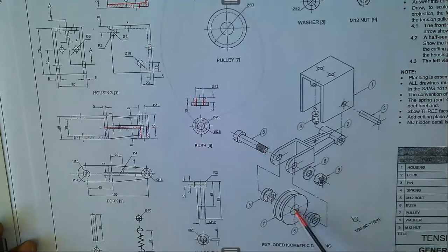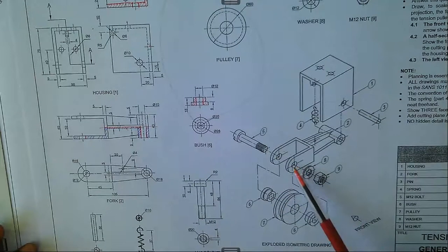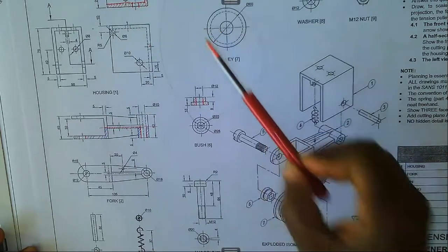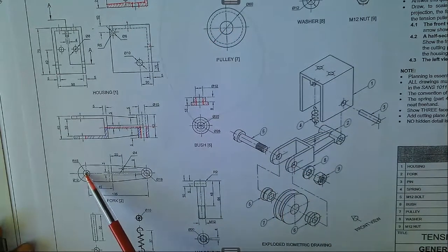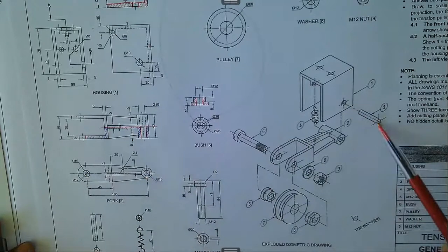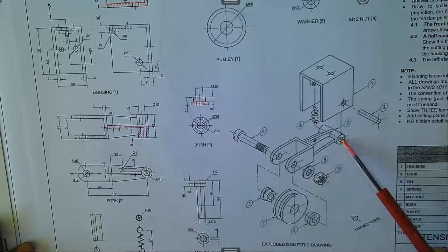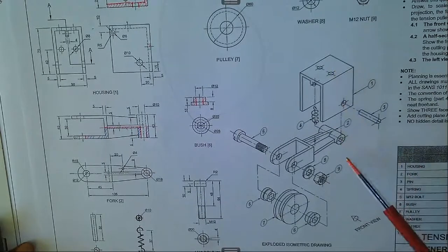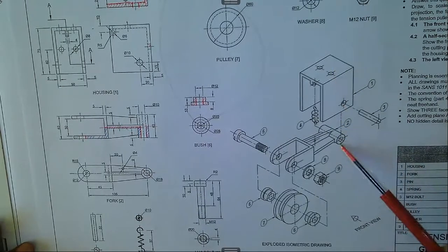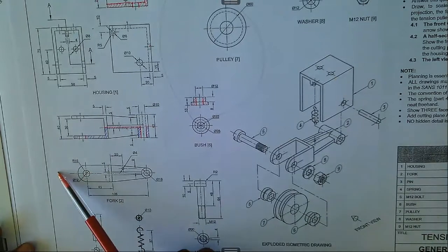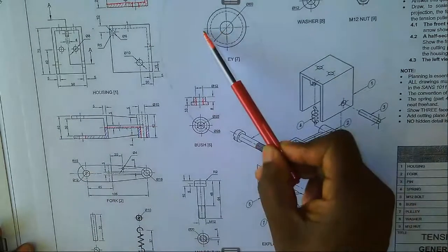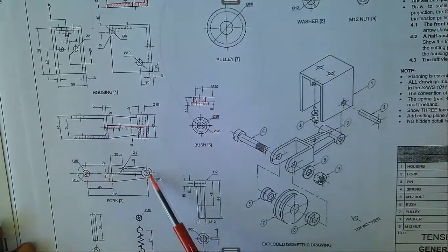So the distance from here to the center line of this one, this point is going to be right there. So what we need from here to the left, we need 30 millimeters, which is from here to there. And we are also told that from this center to that point, which is also going to be aligned with the housing, from here to there we have got 30, which is the 34 for the pulley. Then from here to that hollow part, we have got 105.